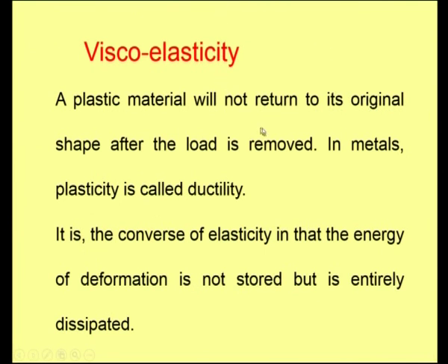A plastic material will not return to its original shape after the load is removed. This is about a purely plastic material. In metals, this plasticity is called ductility. It is the converse of elasticity in that the energy of deformation is not stored, but is entirely dissipated. That is, in an elastic material, the deformation energy is stored. Once the stress is removed, the deformation energy will help the material to come back to its original position.